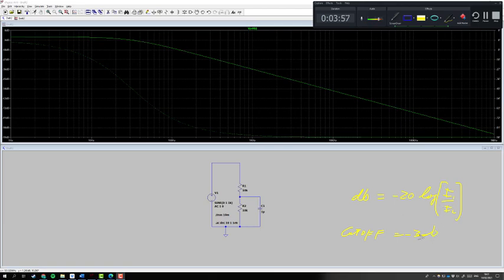And if you calculate back, that's equal to basically half your original signal. So, sorry for that little red thing there. If we start off here, roughly speaking, our 3 dB point, we can start to zoom in, but I won't bother for the sake of brevity. So our 3 dB cutoff will be somewhere around here.